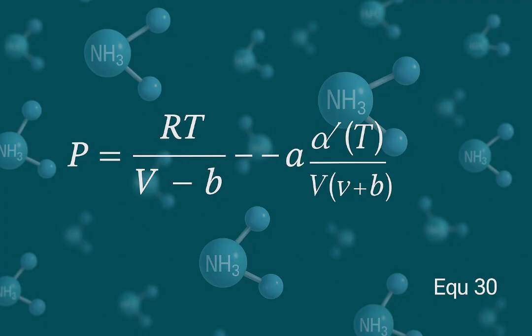6.3.3.2 Practical application of the SRK equation. 1. Gas and liquid equilibrium. The SRK equation is often used to predict gas-liquid equilibrium and phase separation in chemical reactors, particularly in natural gas processing and petrochemical production. By modeling the non-ideal behavior of gases, engineers can predict when gas will condense into a liquid under different temperature and pressure conditions.